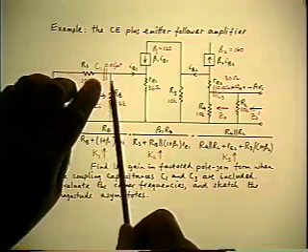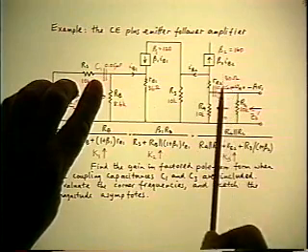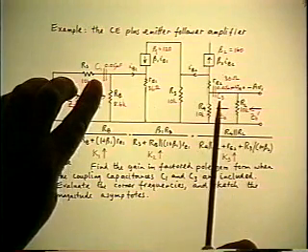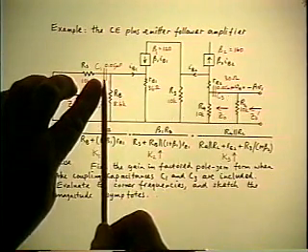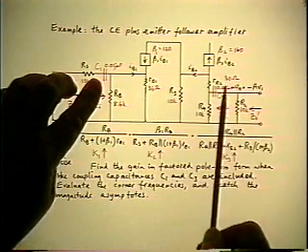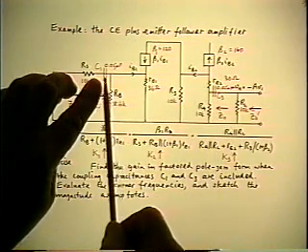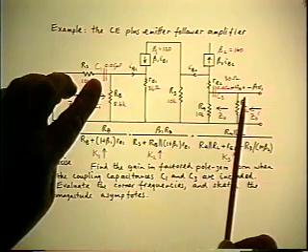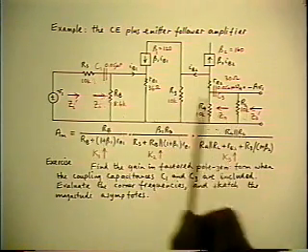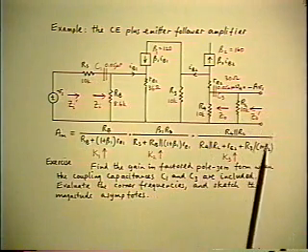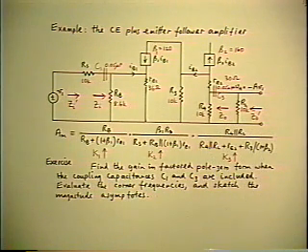That's why after we put the C1 in, and we calculated the driving point impedances for C3, those impedances were still resistances, in spite of the fact that there was a reactance already in the circuit, because the driving point impedances were unaffected by the other element. So this is sort of a special case of the two extra element theorem. The special case is if there is no interaction between the two extra elements, the result is the same as applying the single extra element theorem in succession, which is exactly what we did.